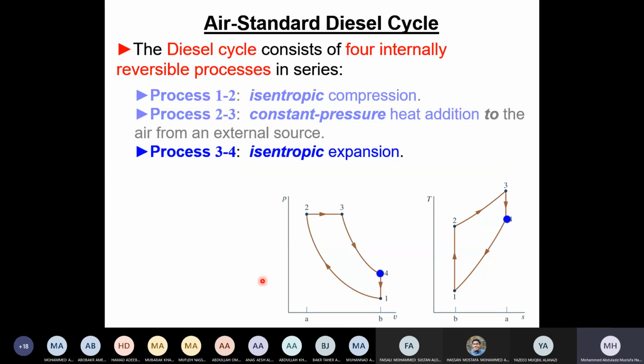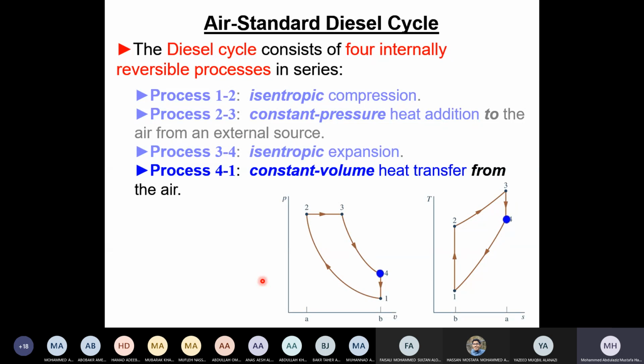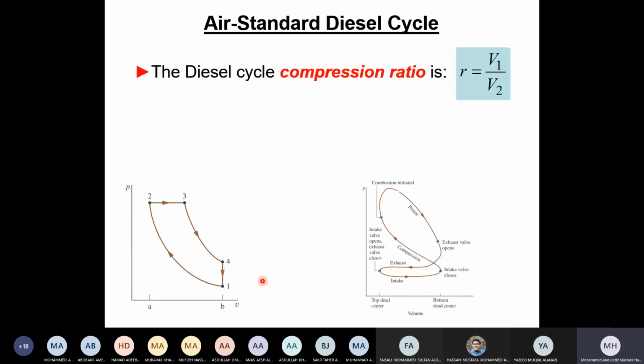So let me go to the next slide here first, and then I come back to this one. Remember, this is the actual cycle for a gasoline, spark ignition engine. Otto found that he can approximate this as a vertical line, and this as a vertical line, and those are isentropic.